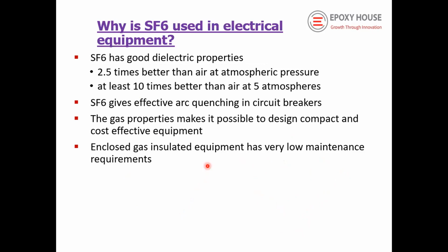SF6 gas also has a liquefaction limitation when it is required to be used at very low temperature. In a circuit breaker kept at low temperature, less than -40, it is very difficult to use. It has to be used with heaters to maintain the temperature above -30 degrees at any rate, because if the temperature goes to -40 or below at a 5 bar pressure, it can reach the liquefaction temperature and lose its properties.